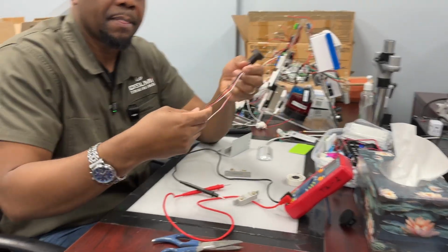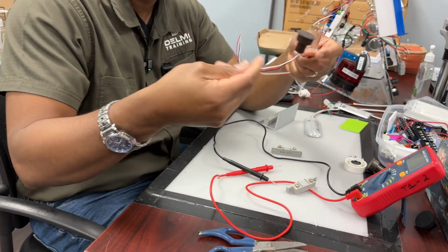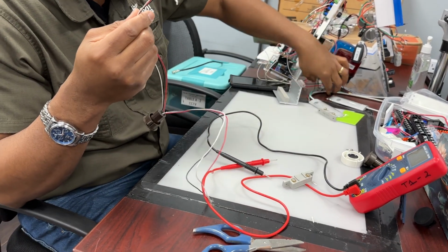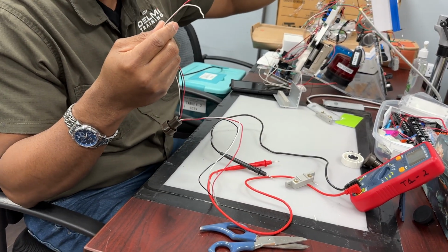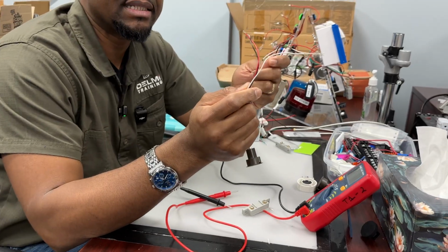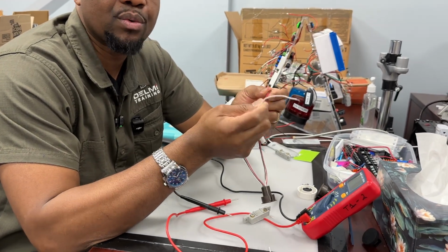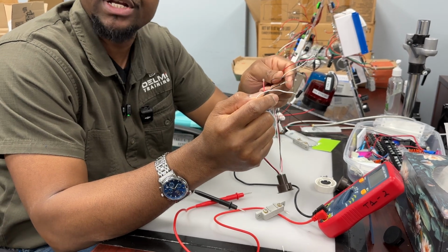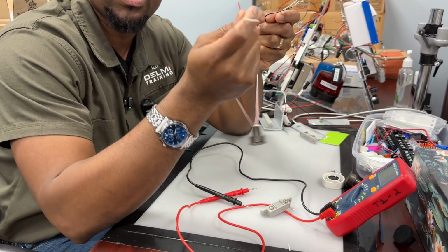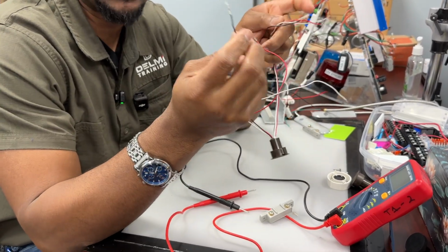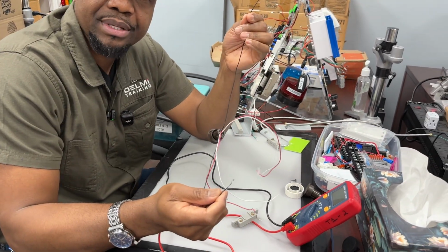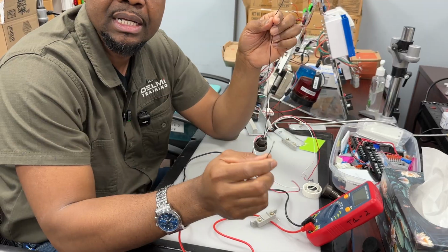On this one, this is a double pole, double throw. I'm going to test it out the exact same way that I tested this. And because the colors are identical, if I'm able to determine which of them is the common and which is the normally open, it's going to be the same for both. So if I find out that the black is the common on this one, then the black on the left is also going to be the common. And that's just pretty much how it happens.